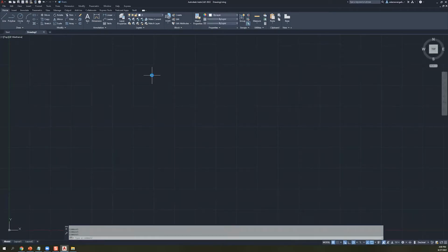Yeah, this is a completely empty drawing, so nothing too special over here. And you'll notice that instead of ACAD.dwt, this is now saying drawing.dwg instead, meaning that this is in fact a new drawing. So looking pretty good so far, huh? This is the model space, right? This is going to be the area where you're going to be doing most of your drawing and working over here, right? You can see it's kind of a big grid-based layout. There's your origin point over here.